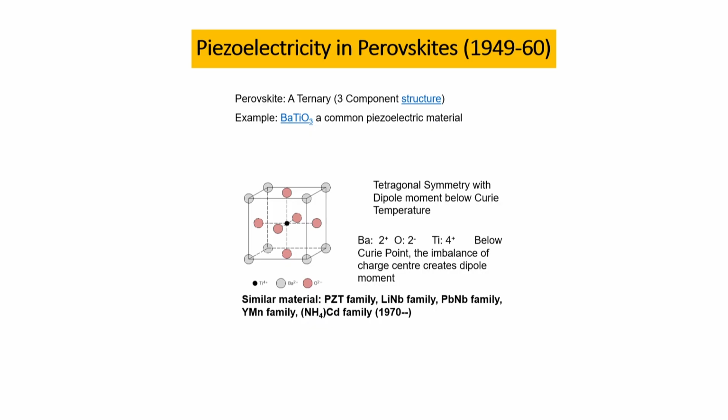Now, only in one material I will tell you, because the details of all these things I cover in a different course on smart materials, but for the sensing purpose I will just briefly touch on these issues. The source of piezoelectricity in the ceramics is that they actually have a ternary structure, ABO3. You can see that there is one metal, a second metal, and then there is oxide. So, you can see in fact here also that these are the oxygens, which are at the face centers, and then at the vertices you have one metal and titanium is right at the center.